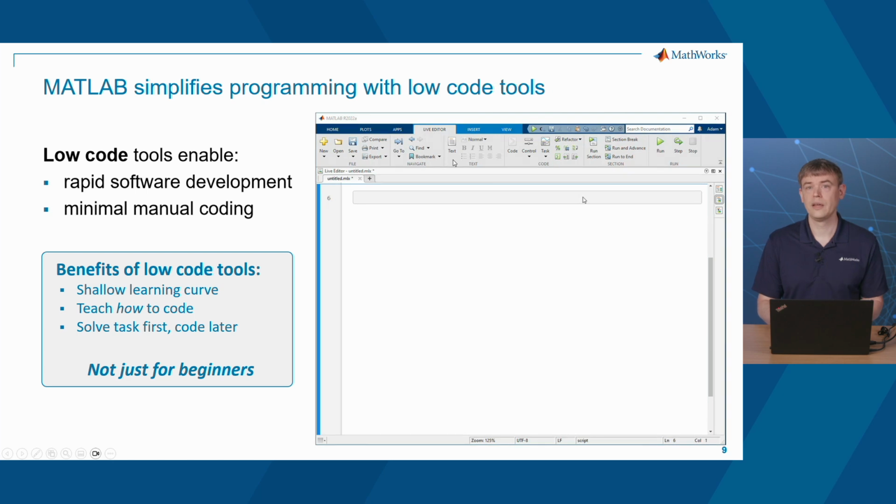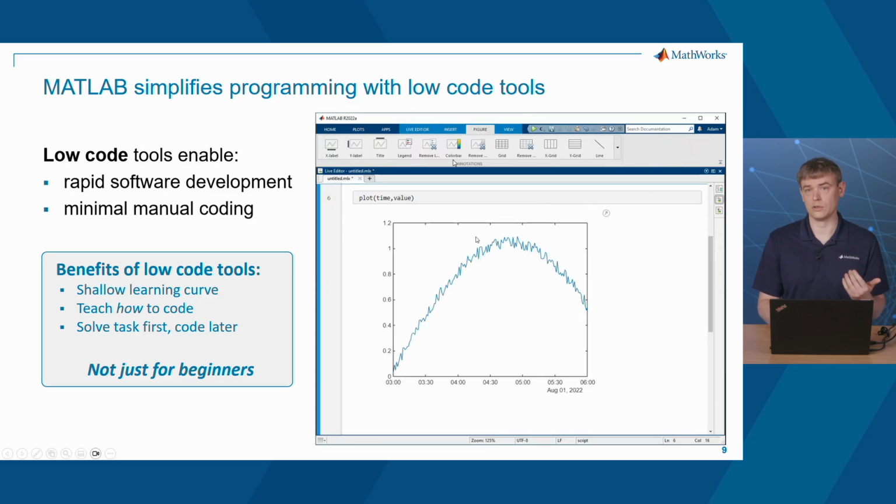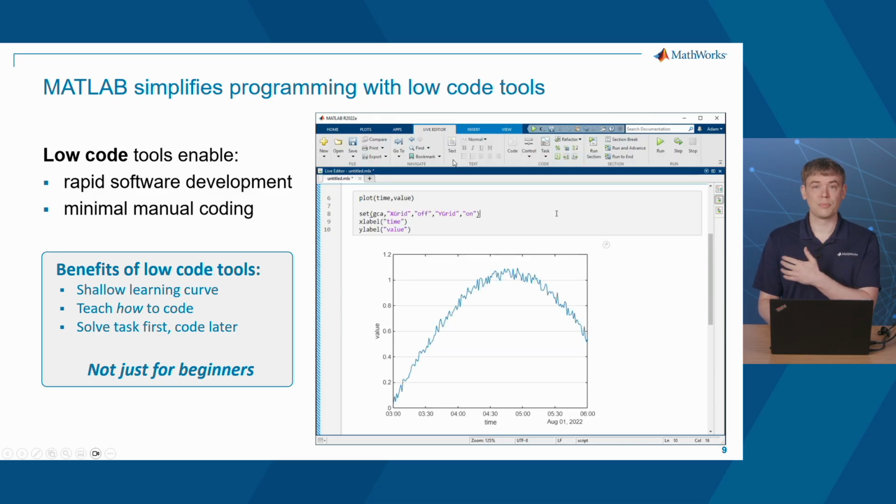If you use MATLAB for any length of time, you'll quickly encounter the plot command. You can give it some X data and Y data, and it'll make a simple line chart. But you might not know how to customize it, like let's say add some axes labels or turn on grid lines as we're doing here. Well, you can see when you do different operations in MATLAB, often there's an interactive way to do it that will generate the code you need to programmatically do the same thing.